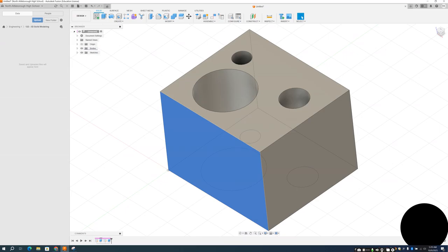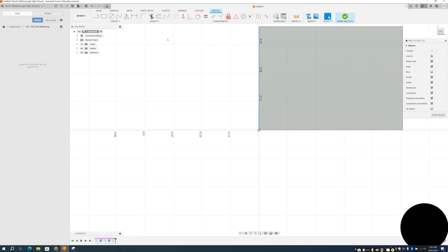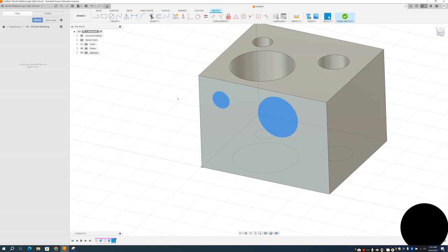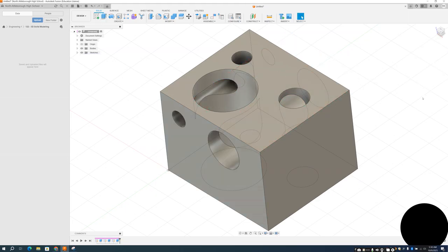Now I'm going to create a sketch on my front face, and I'm going to do the same thing. Add at least 2 circles to each side. Try to avoid intersection with the edges. Hold shift, highlight each one. E is my shortcut for my extrusion. And instead of using the extent type through all here, I'm just going to manually drag my arrow. There. Okay, looks good.